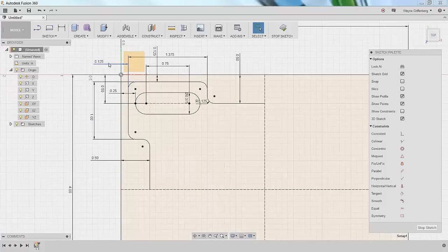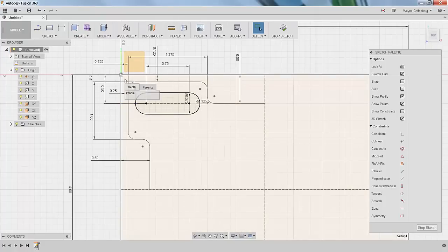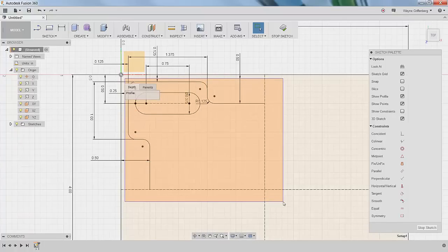Another thing in Autodesk, and you'll see it in a lot of other CAD softwares too, if you start a line, I'm going to click right in here. You're going to start a selection box. I'm going to click right in that little middle of the box right there and start to drag down to the right. I get this closed blue line and sort of orange box. Now whatever falls inside of that box is going to get selected.